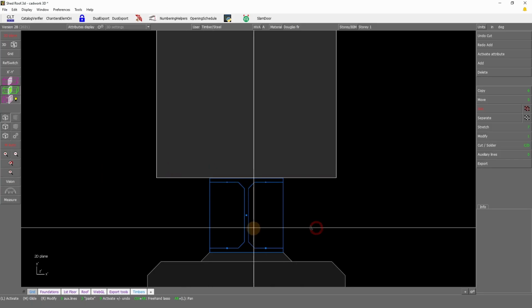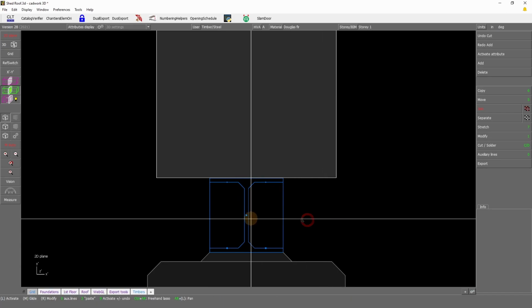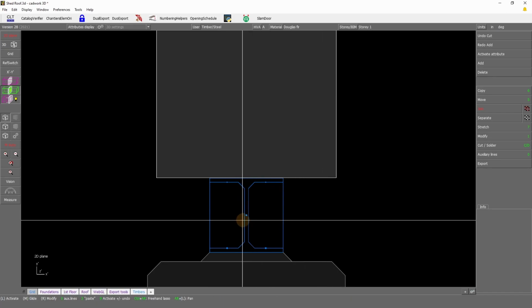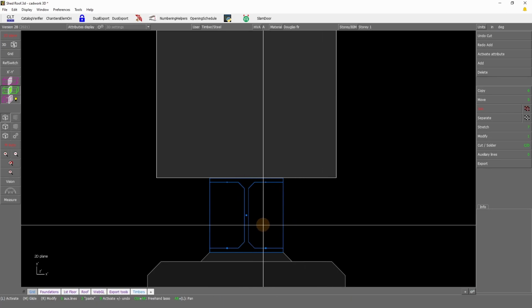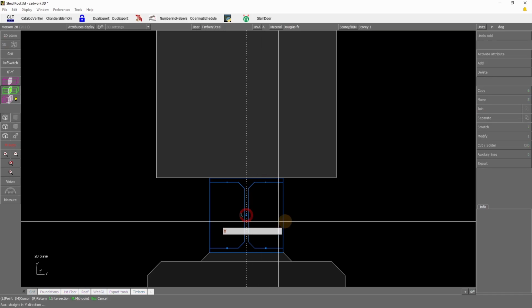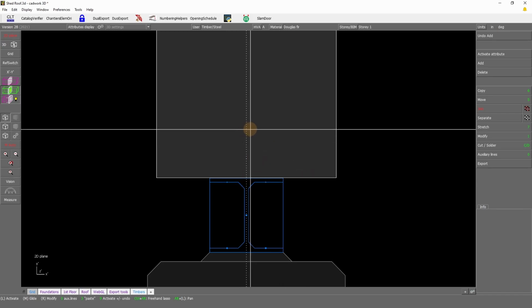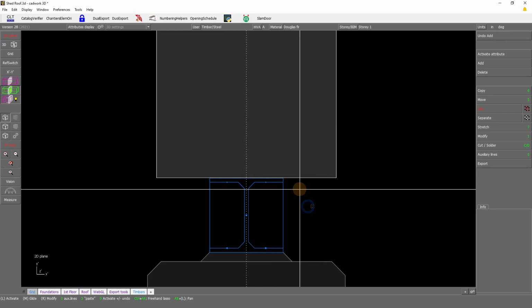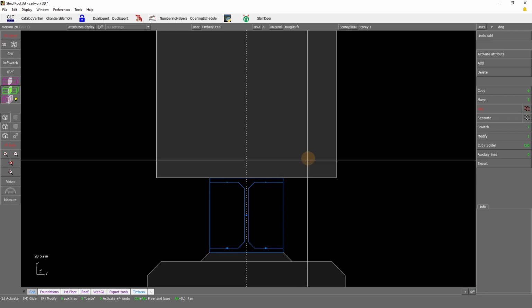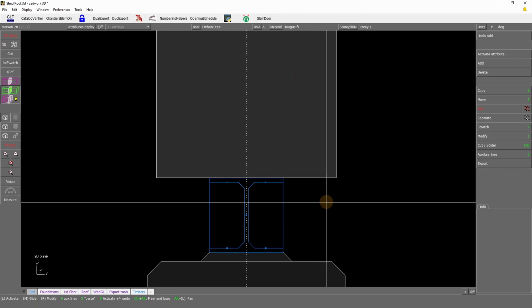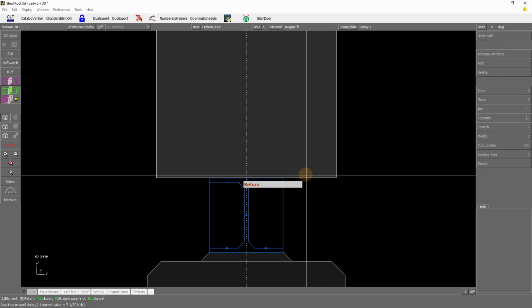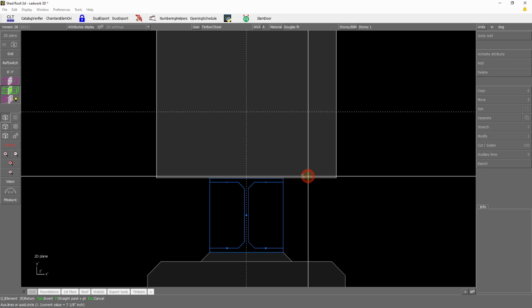So here to add this element, we already have the center line here with this steel shape axis. So Y and left click to add a vertical line at the center of the post. Then we will add the height of the plate. So with E, so line width offset 7 1/8 right above.